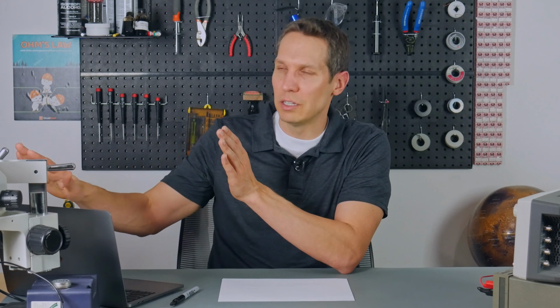And then, since we more talk about electronics and circuits in here, where you would see this on a circuit is with like an RC or an RLC circuit, and you change the voltage on that circuit. The voltage across the capacitor will not instantaneously change from 0 to 5 volts or 5 volts to 3 volts or whatever it is. It will not make that change instantaneously. It'll ramp up or ramp down. And again, there will be a transient time, which is the time where you go from the input until it reaches steady state. And then you have that curve. But then after a certain amount of time, you will get a steady state constant all the way forevermore until you make another input change.